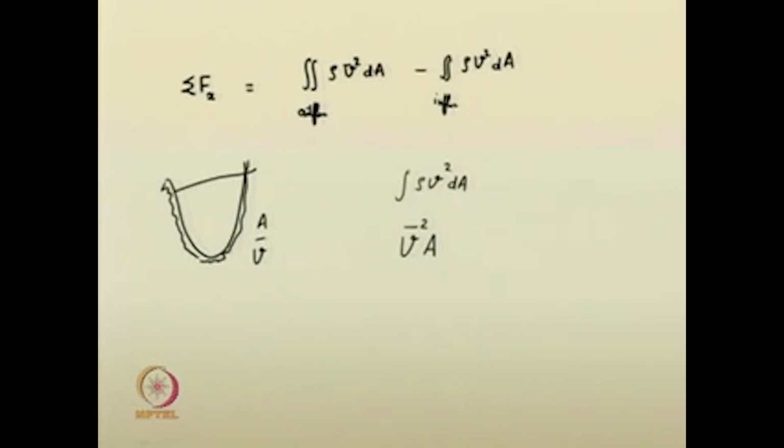not the same, because this quantity signifies the momentum flux across this control surface or across this cross section. What is the momentum flux transmitted? So, the momentum flux integral rho v squared dA is not equal to the average quantity. If you take the average velocity into A, whatever momentum flux you obtain through the average velocity will not be the same.